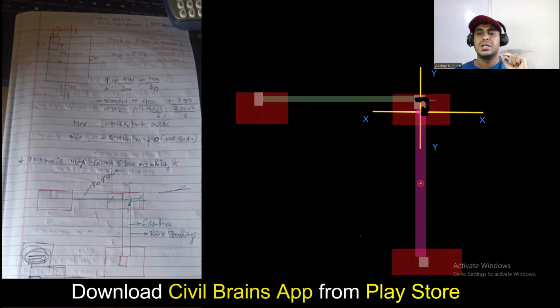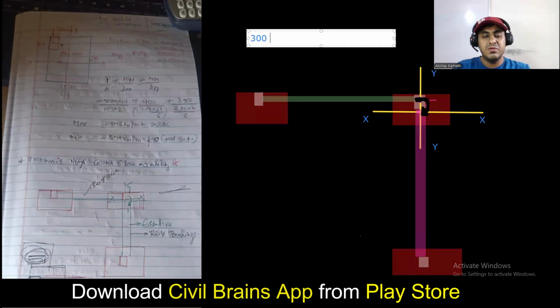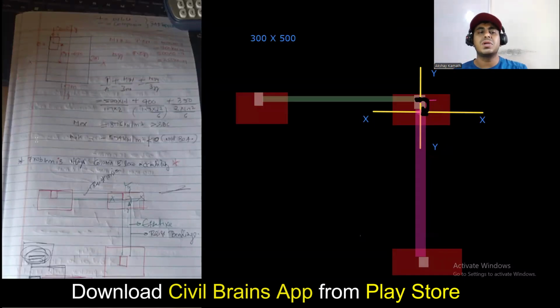For example, let us say the footing depth is 500. So you'll be providing a beam of, let us say, 300 by 500. 300 is the width of your beam. Depth of the beam is 500. You have to do the calculation for that. Again, you can make use of software like SAFE, or you can have your own Excel sheet, and you can do the designing. Okay, you're getting my point, no? So this is how it has to be understood.